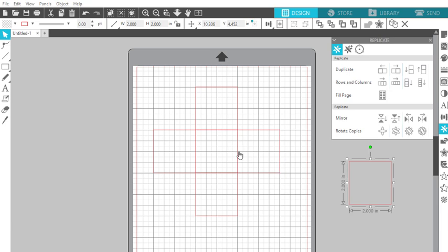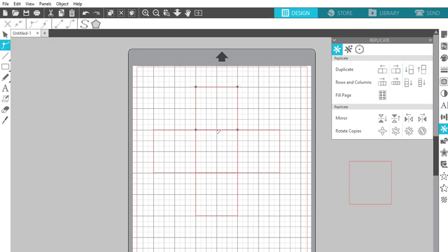Next, we're going to weld the base and the 4 sides into a single shape. In order to weld a shape, we need some overlap. So we'll select this top box, and we're going to use the point editing mode to add another point to the middle of the line, and then we'll just drag it in like this. And we'll do this for the other boxes so that we have some overlap for all 5 shapes.